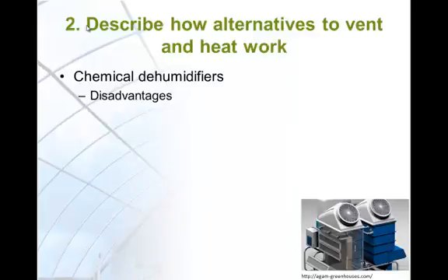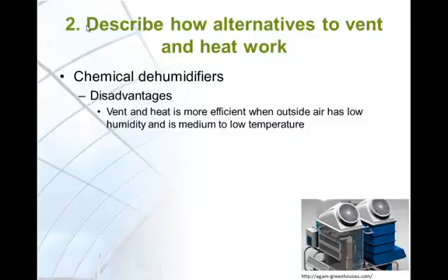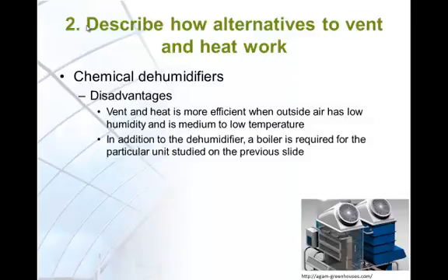Chemical dehumidification has its disadvantages. Conventional humidity control is more efficient than the chemical dehumidification when outside air has low humidity content and is medium to low temperature. In addition, the particular unit studied by Longo requires a boiler for the operation.